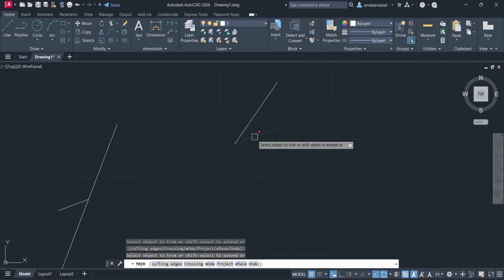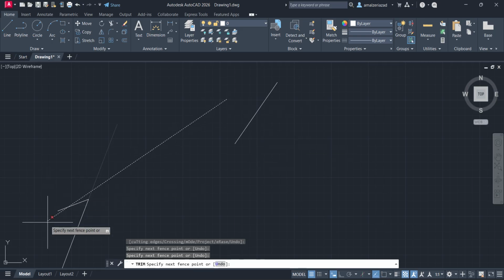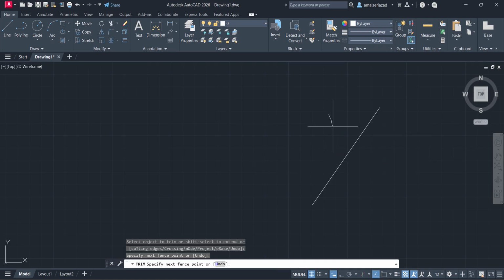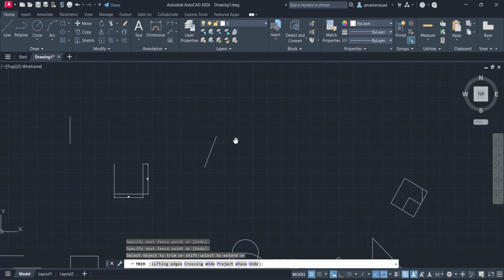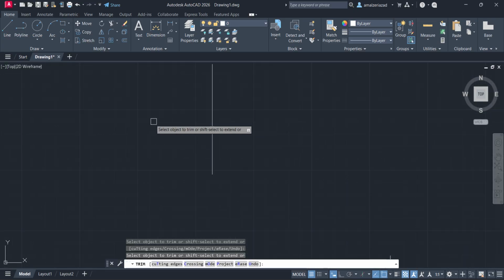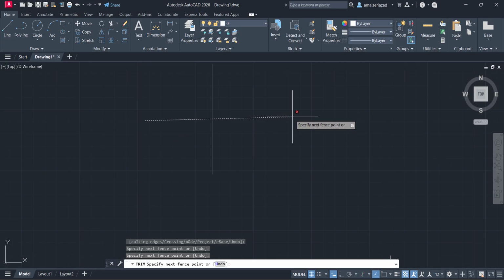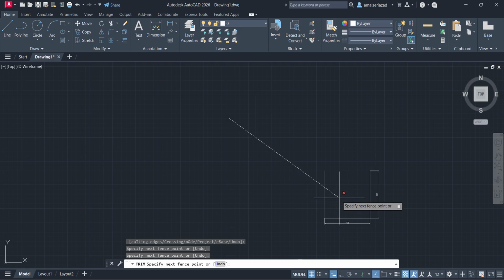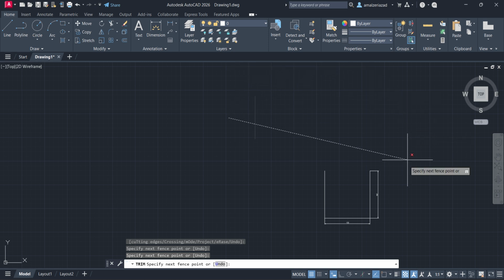You can directly go and click on it, otherwise you can keep one point here and drag like this. Wherever you go, whatever comes under that particular line will be trimmed. That is one more method, and one more is you can drag it also. Everything I'm doing with the left mouse button only. I can click the left mouse button to trim, or I can click once and then drag. It is not like completely dragging. I keep a point once, and then I simply move my mouse there, not pressing and holding and dragging. Then also I will trim, right?